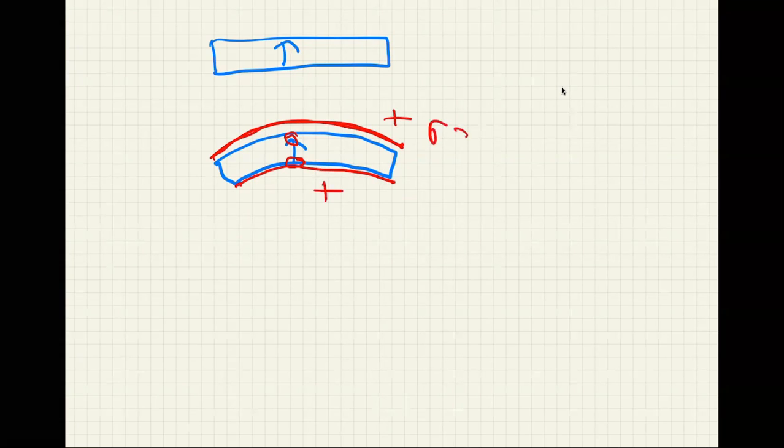Here you have pressure which is positive, and here you have pressure which is negative, and you are also changing the direction of the arrow, or you are applying these two different pressures on two different sides of the polarization vector, and therefore you will have zero charge or current between these two planes. So homogeneous bending of a single-element piezoelectric material will not work.